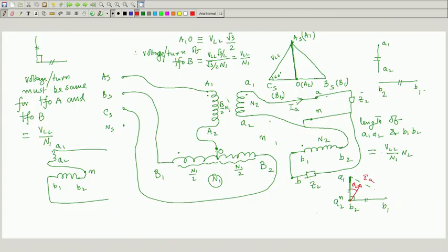But the moment it supplies a current, these are transformers. So, rules of transformer must be satisfied. What is that? Voltage ratios are in the ratios of turns. Similarly, if through the dot a current comes out, its primary will draw additional current through the dot, whose magnitude will be I A by turns ratio of this transformer. For transformer A, I am telling.